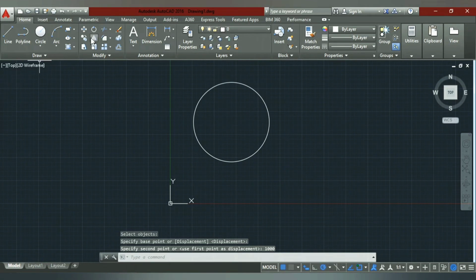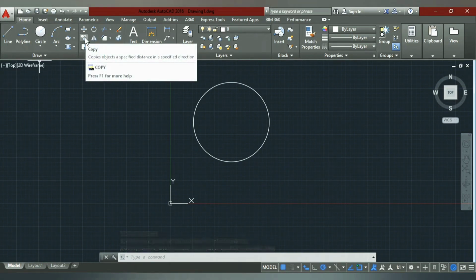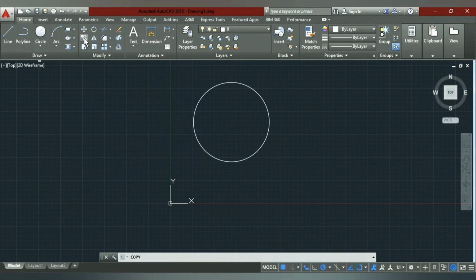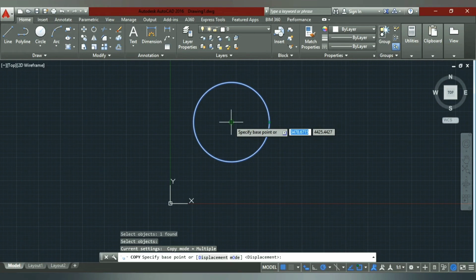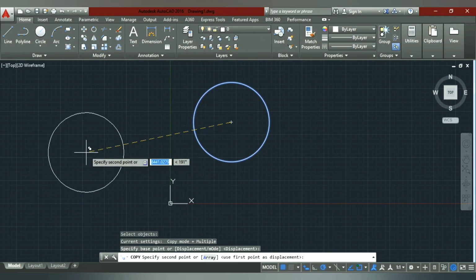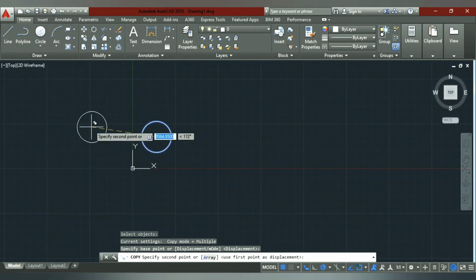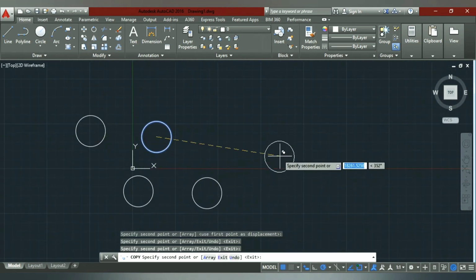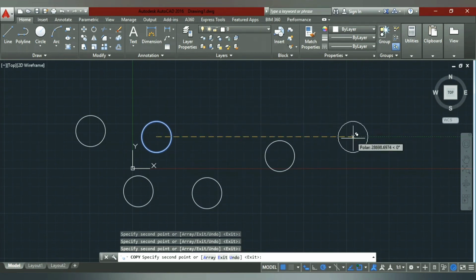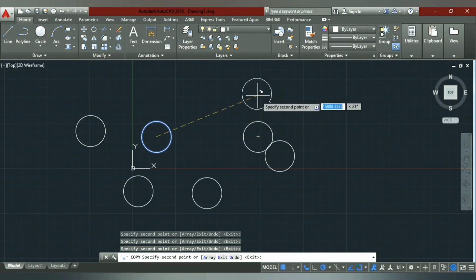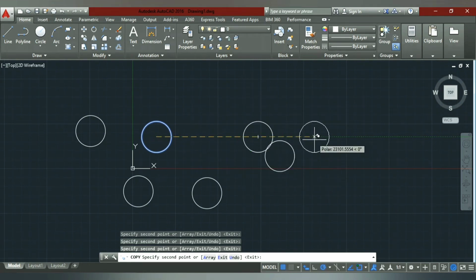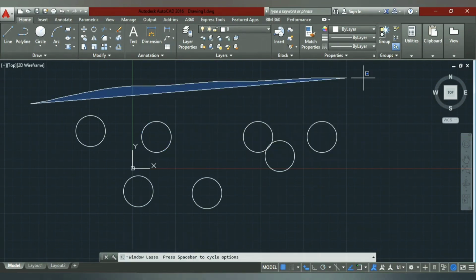Okay, and then if you want to copy this circle, just select this object and space once again, and select the center from where you want to copy. I want to copy it from the center once again. Just do this, 1, 2, 4. I can copy wherever I want. Just be specific with your length. For now I'm teaching, but sometimes when you're drawing you know the specific length and angle where you want to copy, so you can just give that.